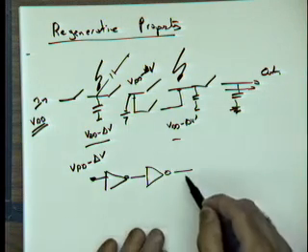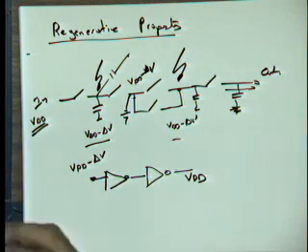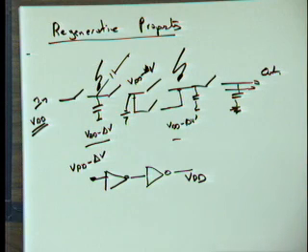And if you go through enough gates, we're going to be perfectly back at VDD or at ground. So the impact of the noise gradually disappears while we're going through consecutive gates. That's a good property because now it means that I can build very complex networks, and if I inject some noise at some place, it gets smaller as I go through consecutive steps.